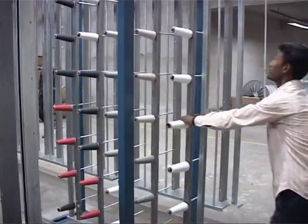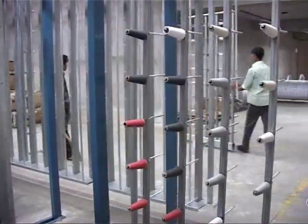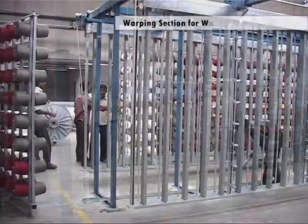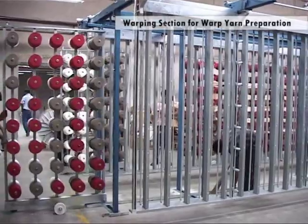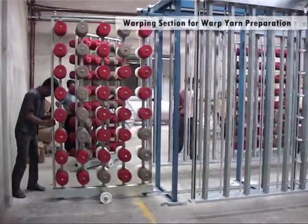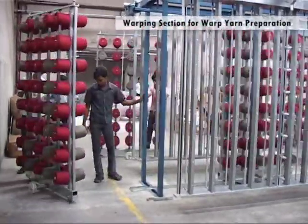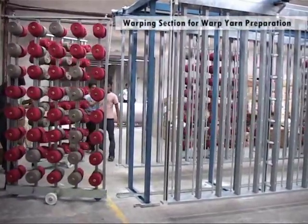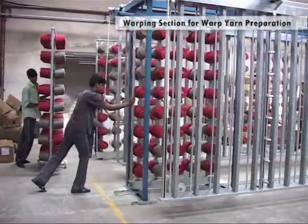If the creel capacity is equal or higher than the number of warp threads, the warping would simply entail the direct winding on the warp beam of the threads coming from the creel. Generally, this condition does not take place, and even with creels of high capacity, the number of creel positions never corresponds to the number of threads, which is always by far higher than the number of bobbins which the creel can contain. This problem has been solved by dividing the warping operation into two phases.